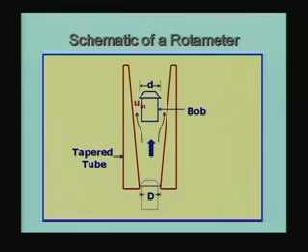In the case of the three measuring meters which we talked about, the Venturi, the nozzle and the orifice plate, normally we use the horizontal orientation. The meter will be located horizontally in the pipeline, and many times the pipeline is actually horizontal, and therefore it does not involve any problem.